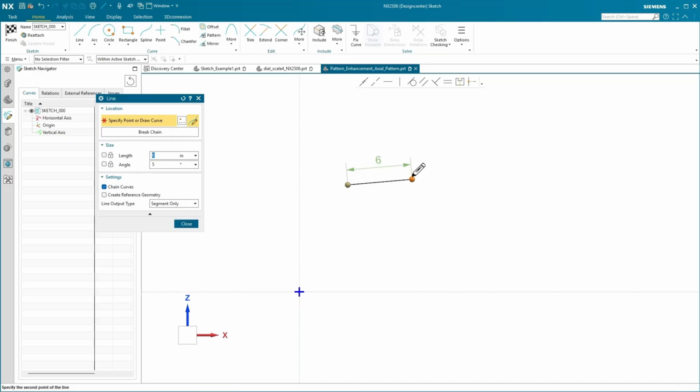All right, so that's the first thing with drawing a line with the new curve setup here. If I stop, you'll note the actual solver is finding conditions as we start to draw these curves. Again, if I stop moving, lock relative angle, turn that back off, I can change the angle here. Now you'll note that the software is automatically generating a preview dimension on that curve as I'm drawing and extending the length. If you want to enter your own value for the length of that curve, all you have to do is type in the value on your keyboard. As you'll note over in the line dialog box, the number 8 for the length is actually highlighted in blue there.